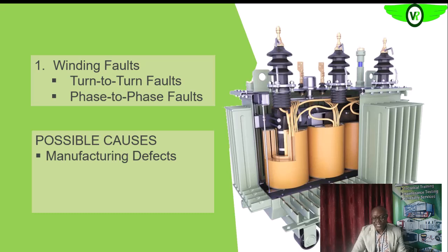Or substandard materials could be used during manufacturing. The right gauge of conductor, that is the wire on each of the windings, is not used. The right insulation or insulating materials are also not used. All of those can introduce defects that will show up during normal operations.